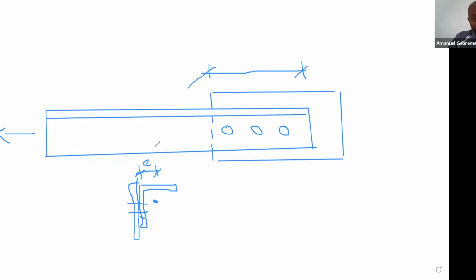So for the design of this member, you can't just say, all right, I have my area, I have my yield strength, which is 355, let's say, on a larger angle, and take 355 times, let's say, 0.9 times area as my tension capacity of that angle. That is actually not correct, simply because the way in which you're connecting it, and this is the most typical way in which we connect angles to supports, will introduce additional forces. That's what we call shear lag.